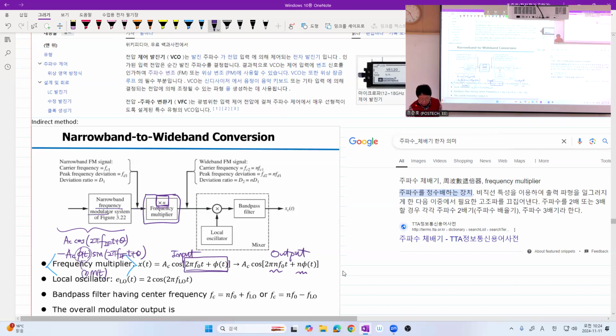Anyway, this frequency multiplier, this trick of using a nonlinear device, made the early deployment of the frequency modulator possible. Okay? Theoretically speaking, as I told you, a voltage controlled oscillator is enough. However, the technology of your time may not allow implementation. But there are always clever guys or hardworking guys to make this possible.